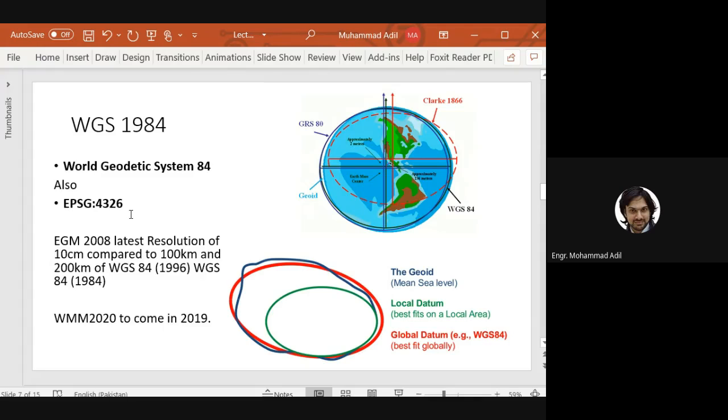So just like we have to convert projections from Cartesian coordinate system into polar coordinate system. So in Cartesian coordinate system we have x and y in feet or meters, but in polar coordinate system we have a distance from the origin and an angle of that vector. So it's in r theta format. So we can convert r theta into xy by taking sine and cosine, and vice versa as well. Just like that, you need to convert your latitude and longitude, which are in EPSG 4326 system, into northing and easting, which is EPSG 3857 system.